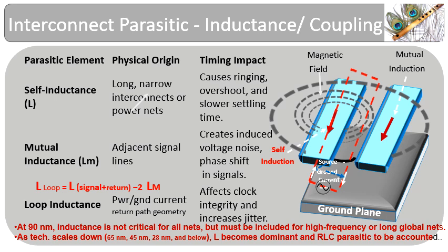The loop inductance is a phenomenon created due to the flow of source current and the ground plane return current. The source current and the ground plane return current produce opposite magnetic fields and together form a closed magnetic loop. The increased enclosed current flowing path area increases the loop inductance. These inductive parasitics distort waveforms and degrade timing accuracy. The clock net paths experience jitter, skew, or edge ringing, which impacts the timing performance.